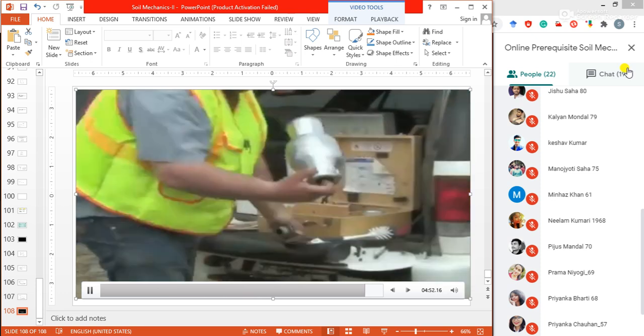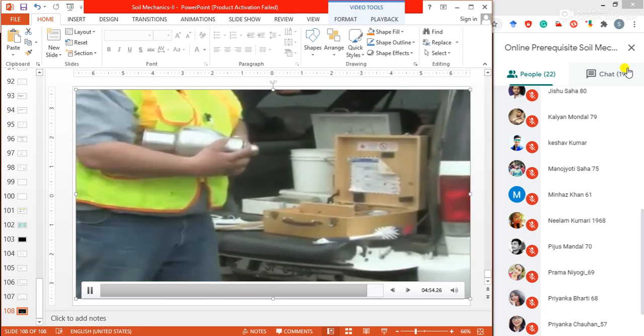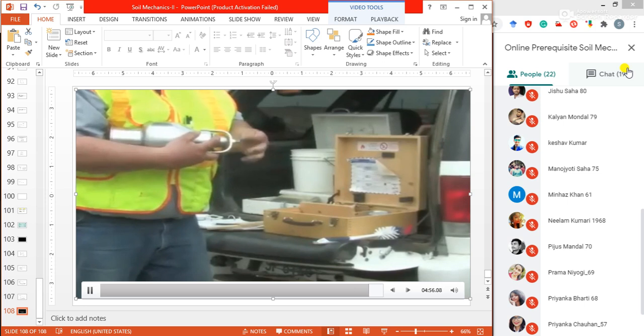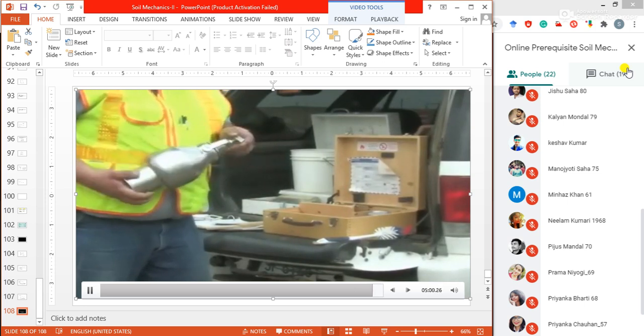Return the speedy tester, steel balls, brush, bubble level, scoop, and reagent to the kit. If the kit contains a balance beam scale, fold the scale before closing the box.